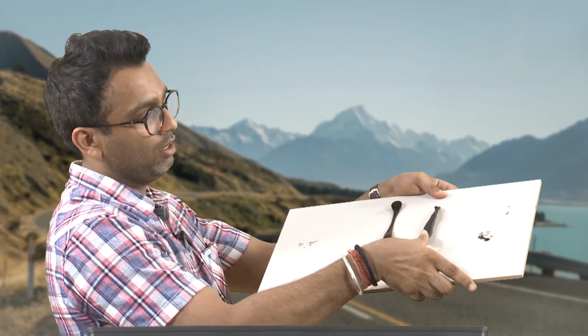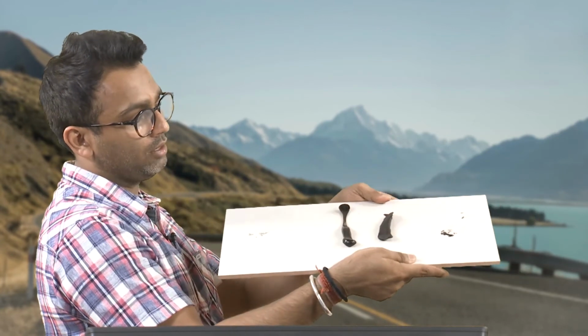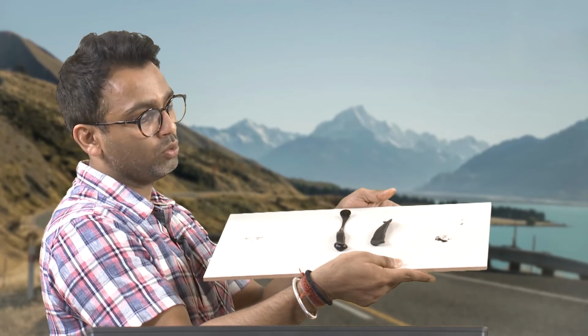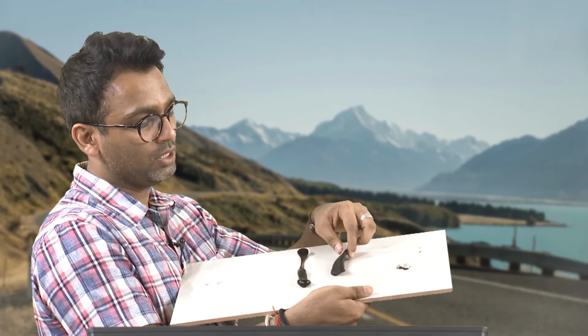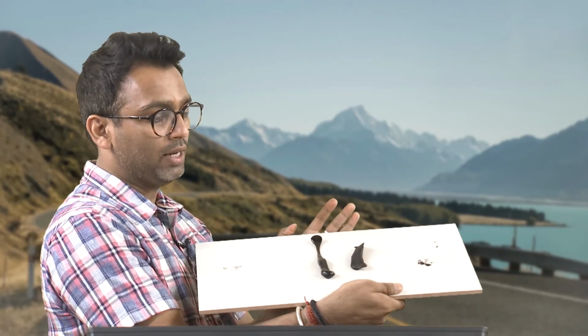As soon as I leave this, you can see that it tries to contract and it tries to recover. Here you can see initially I stretched it to the same length, but now the length has reduced. So, I am trying to keep it here for some time so that we will give an opportunity for recovery to both the bitumen, and we will see how much recovery we have obtained.